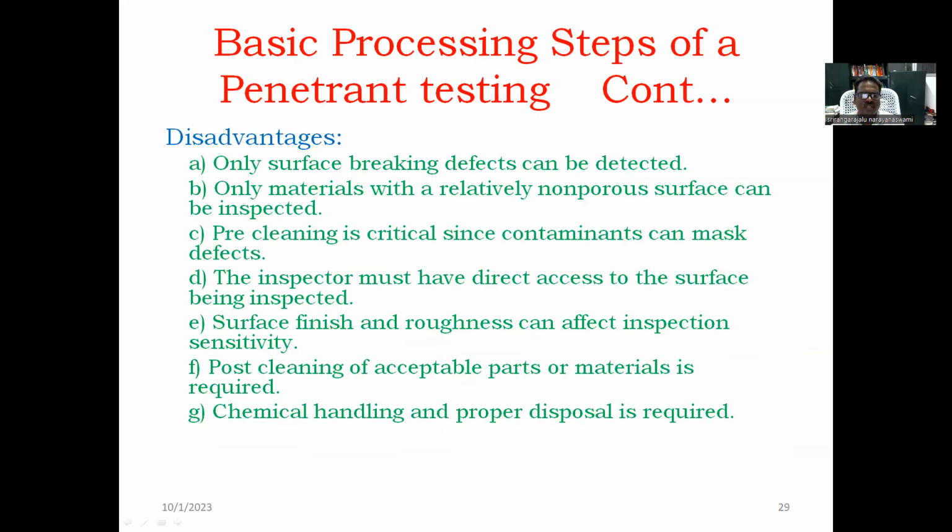Some disadvantages also exist in dye penetrant testing. Only surface-breaking defects can be detected. Only materials with relatively non-porous surfaces can be inspected. Pre-cleaning is critical since contamination can mask defects. The inspector must have direct access to the surface being inspected. Surface finish and roughness can affect inspection sensitivity. Post cleaning of acceptable parts or material is required. Chemical handling and proper disposal is required.